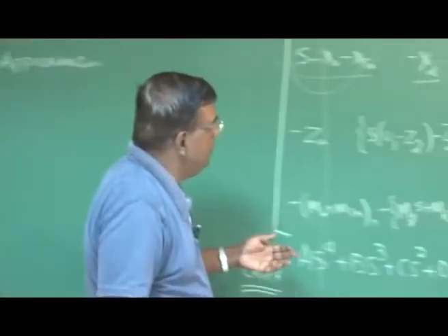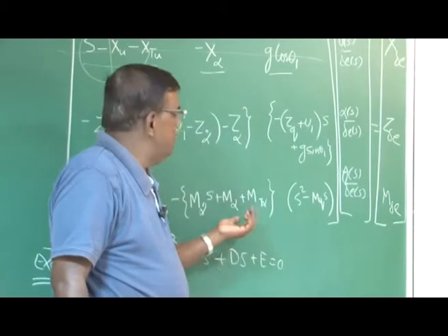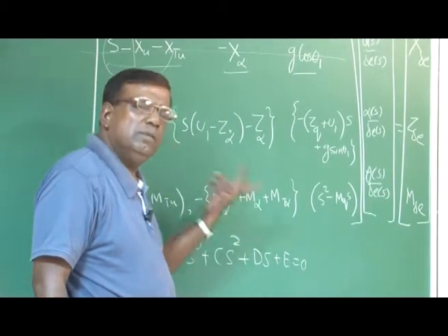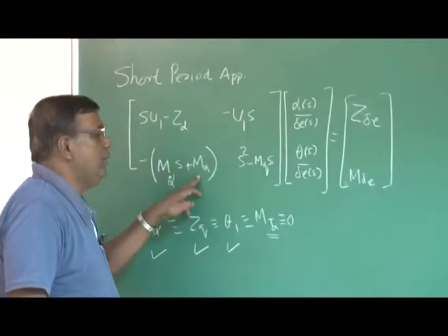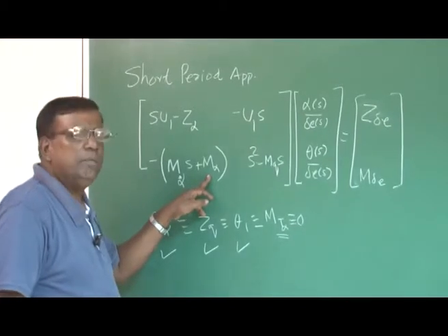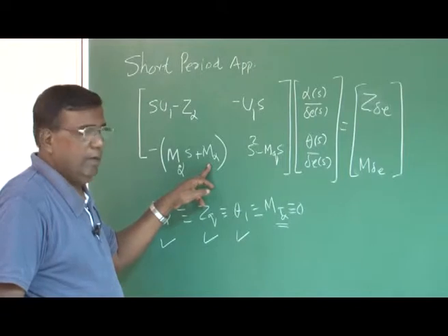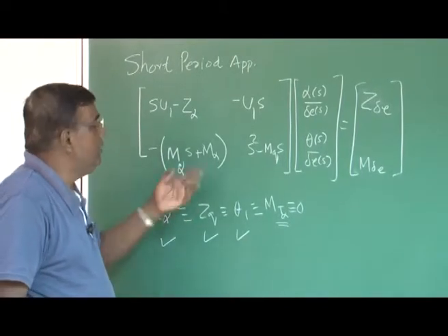We know here m alpha and mt alpha. So, this mt alpha, if you know the value, can be clubbed into m alpha. So, for us the interpretation could be that m alpha has both the component because of aerodynamic moment as well as because of moment due to thrust, as a function of alpha. In a sense, how does it change with alpha?